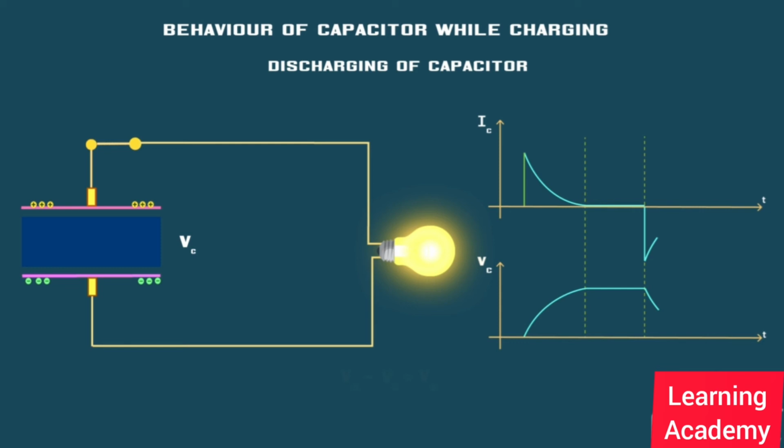As the potential reduces, fewer charges will flow from the capacitor to the bulb. It indicates that the potential at the capacitor is not allowing the charges to move away from it immediately, which implies the capacitor won't allow instantaneous change in voltage. In this way, the potential across the capacitor will decay gradually, which slows down the charges moving away from the capacitor. It will continue until the potential across the capacitor becomes zero, and simultaneously, the current will become zero. This process is known as discharging.